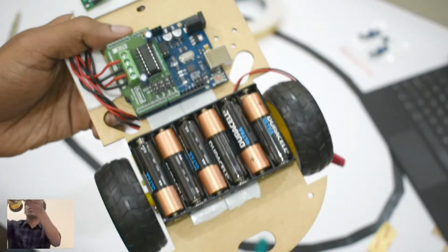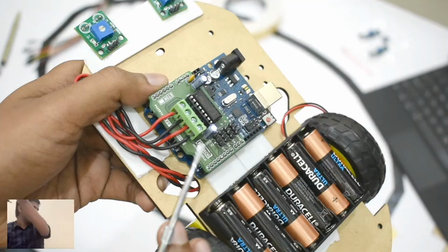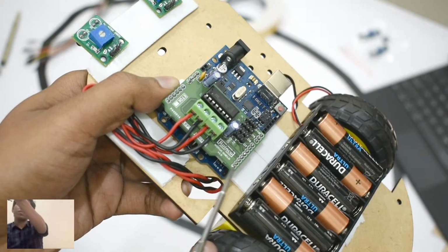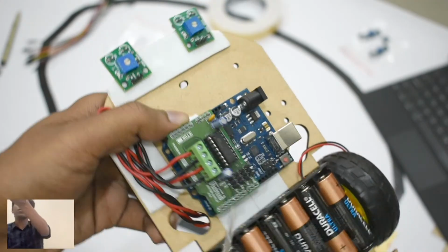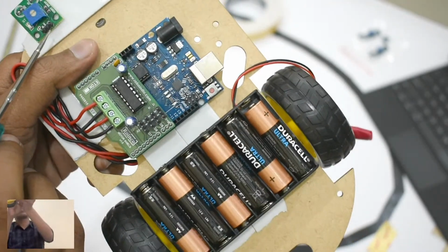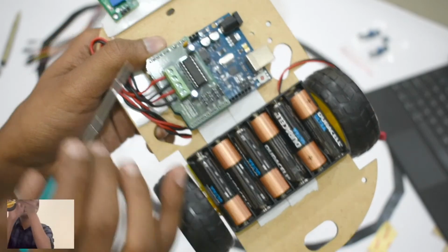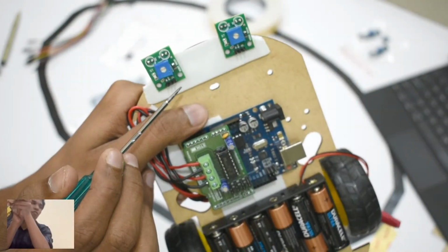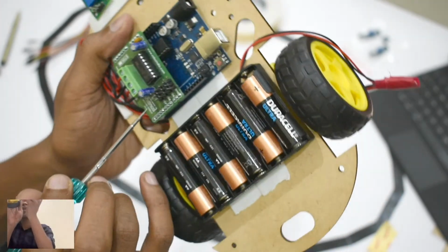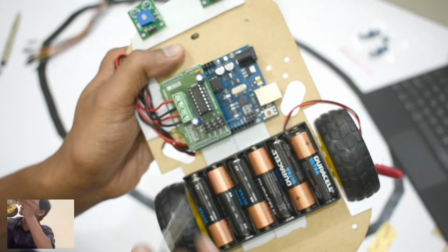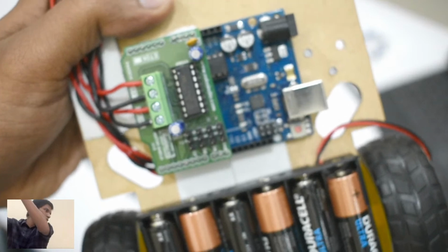So you see all of these pins, there are three pins here, and there are three pins for each of my IR sensors. So we have to just attach the pins in order. There is a power supply pin, 5 volt and ground, that are going to be attached to the power supply pins of my IR sensor. And then there is a data pin. All of these are printed on the circuit. I'm not sure if you guys are able to read what's written on the circuits. Let me, yeah.